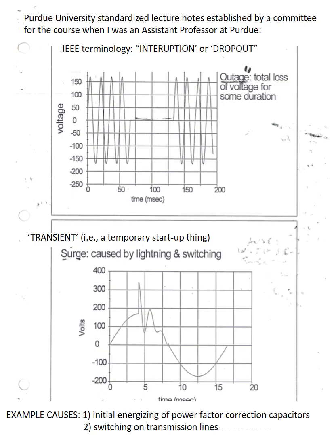Also, switching transmission lines. There's substations. There's big giant switches. At Purdue, I took students on field trips. These are big science fiction looking switches, some of these things. The big giant ball that swings on the end of an arm that connects to super high voltage at a substation. Otherwise, it's going to arc across. And just simple switching, like you would see a circuit breaker kind of thing, on a smaller scale.